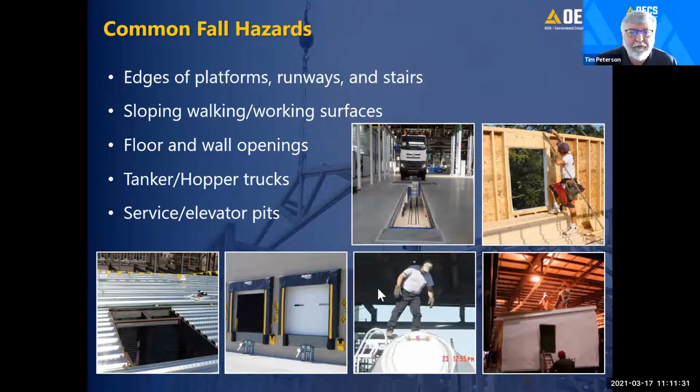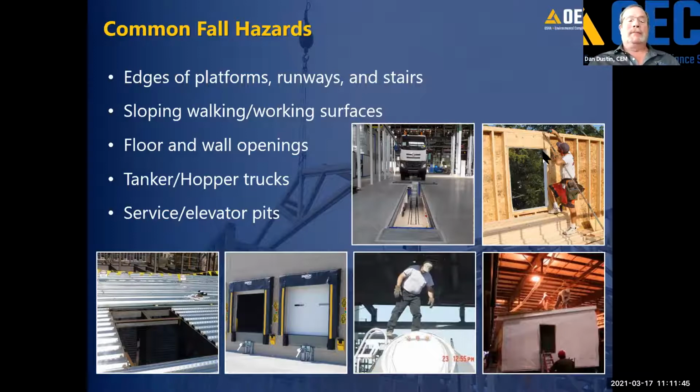And is there a difference on the vertical wall versus a horizontal truss system when it comes to that fall hazard issue? There is. When I'm looking at floor or wall opening, it depends on how big the opening is itself. Essentially, under the construction standard, any floor opening greater than 2 inches in the least dimension has to be covered or otherwise protected. Obviously, I'm not in danger of falling through a 2-inch hole, but it is possible to drop a tool or equipment through that hole and injure someone working below you.